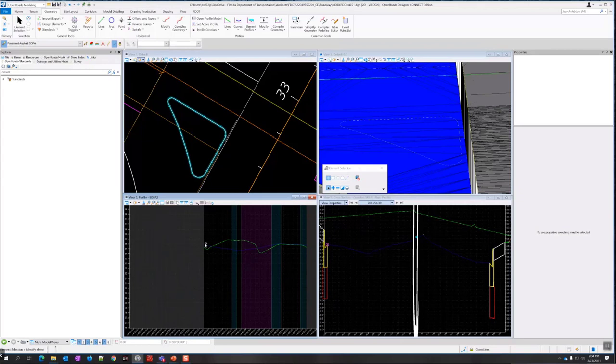You know, so if you need to change the profile for any reason, you can also modify that. But we're going to leave it alone. There's an option in the optional steps in there. You can do a best fit profile, but that should be sufficient for clipping. So we're going to leave it at that. We're going to clip the terrain. So we'll go down to that section of exercise 4.8. So it's on page 4-21.